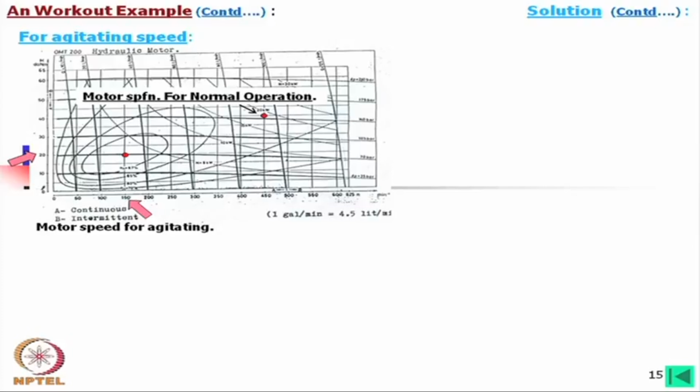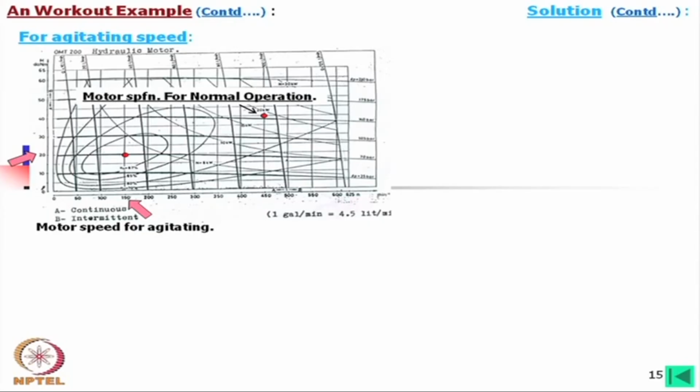Also output speed was 15 and 5. So, we may be tempted that in that case the flow will be just 3 times less, and as the torque is half, then maybe we can consider the power is totally 6 times less, but actually it is not, because due to the efficiency factor we have to again reconsider this.